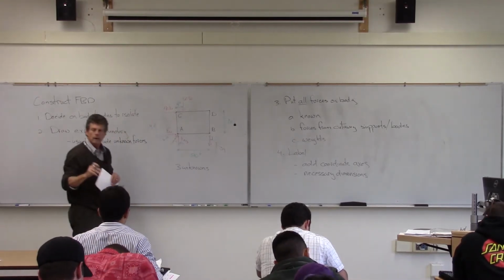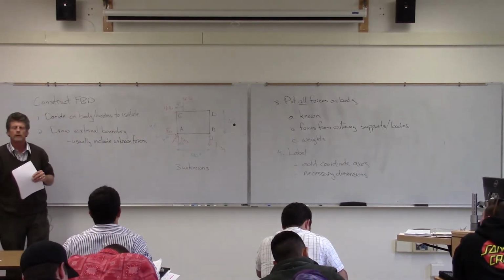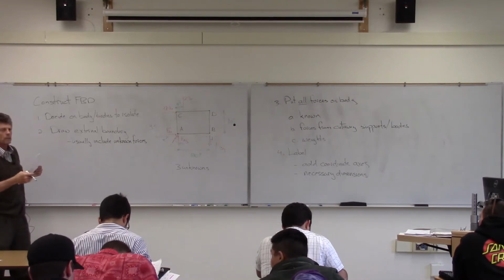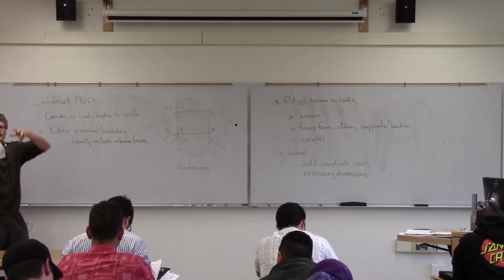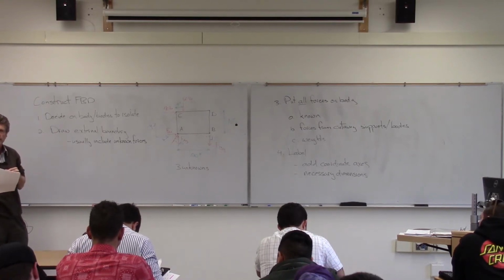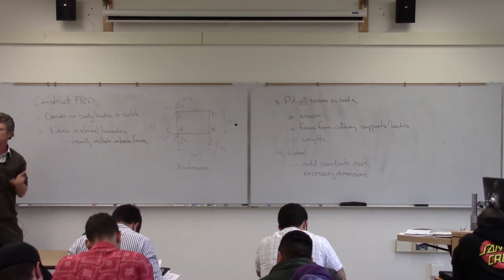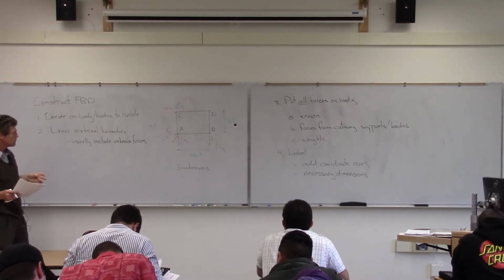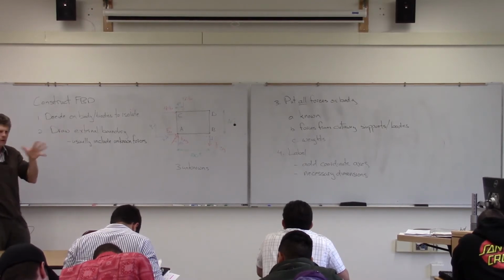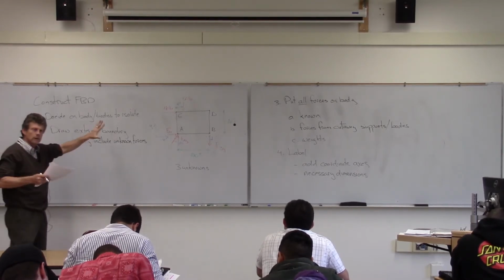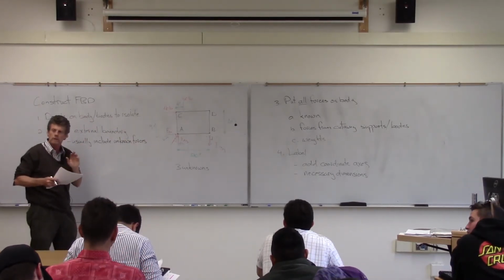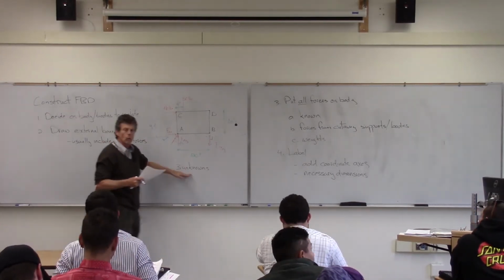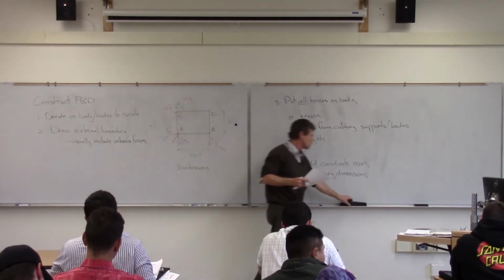And what we end up with then is three unknowns. Now, when you draw free body diagrams, most of the problems you'll have, it will be very obvious what you're drawing. But when you get into the more complicated things, you might find yourself drawing 2 or 3 different free body diagrams and find one has 5 unknowns and one has 2 unknowns and that sort of thing. So you might find yourself stuck with a couple of things, but you can draw different free body diagrams. You'll find that there's combinations of bodies that may give you what we need in terms of unknown equations.